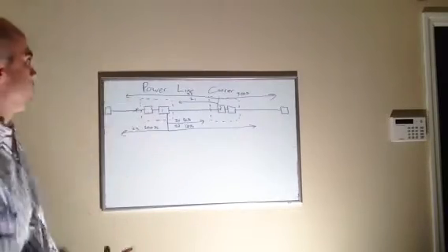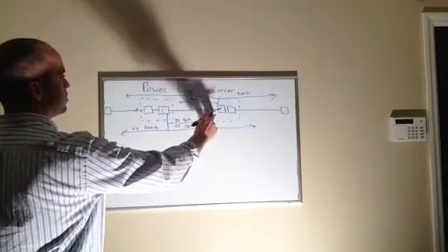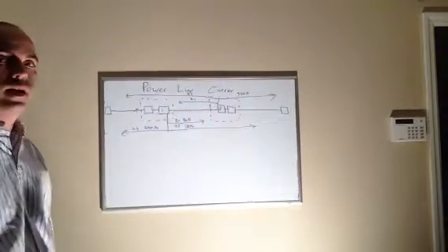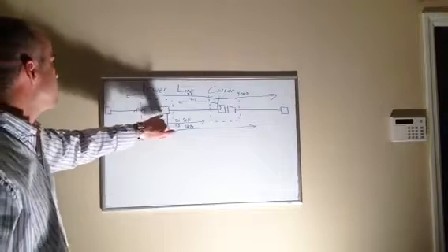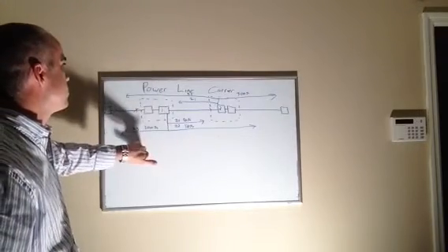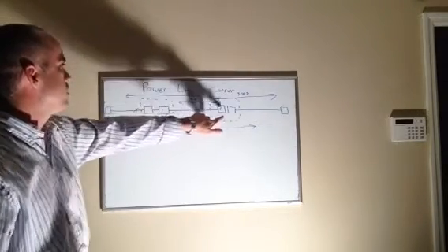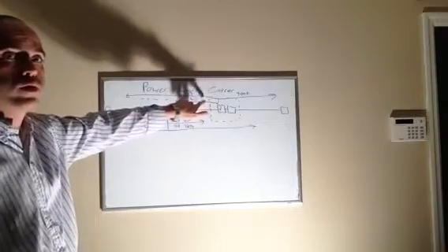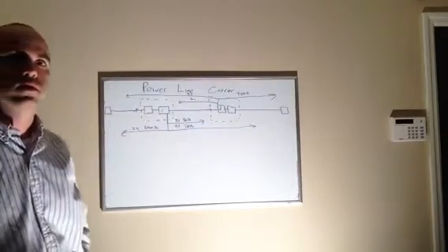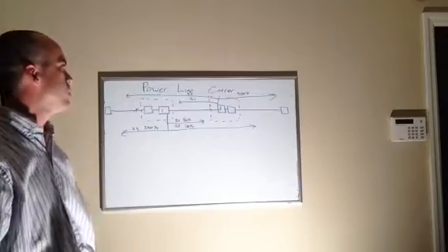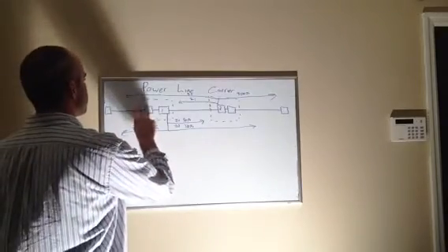I see it reverse looking. So it's sending a blocking signal. So instead of Zone 2 tripping instantaneously, now because you're getting a blocking signal because breaker number 1 sees it reverse looking, that blocking signal is going to make breaker 2, Zone 2, trip in 20 cycles as opposed to tripping instantaneous. Okay, so that's how carrier works.